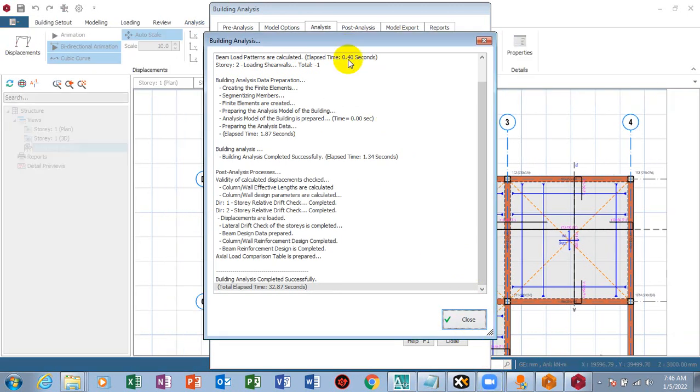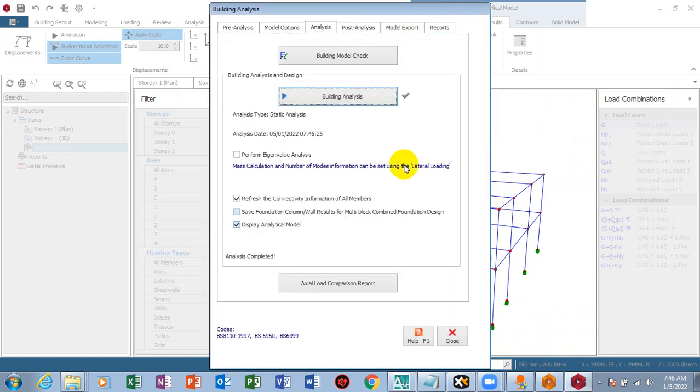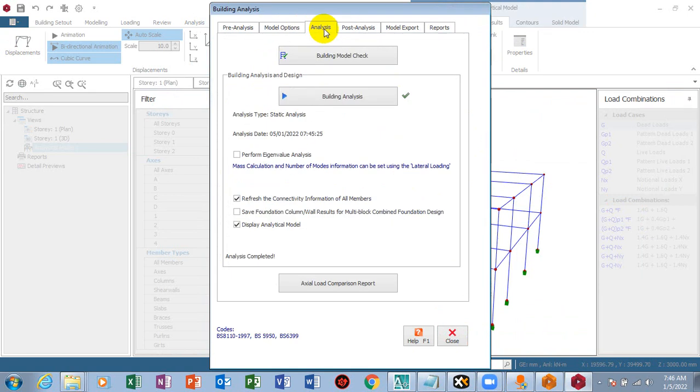So, like I said, it's a design. The larger the span, the deeper the depth of the beam. Most times when you are going more than 5.5 meters, it's advisable your depth of beam should at least increase.